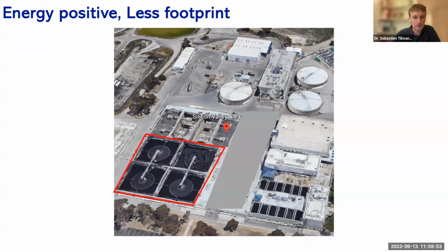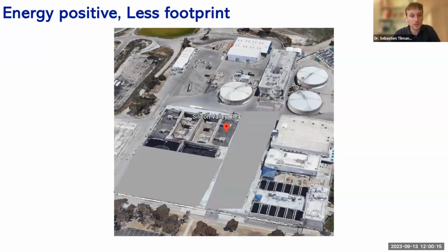The next thing I'm highlighting here are the secondary clarifiers. These are the large settling tanks that are used to settle out the sludge from the aerobic activated sludge process. We wouldn't need those either because we use membranes. You could fit the membranes conservatively in about 1/4 of that square footage.